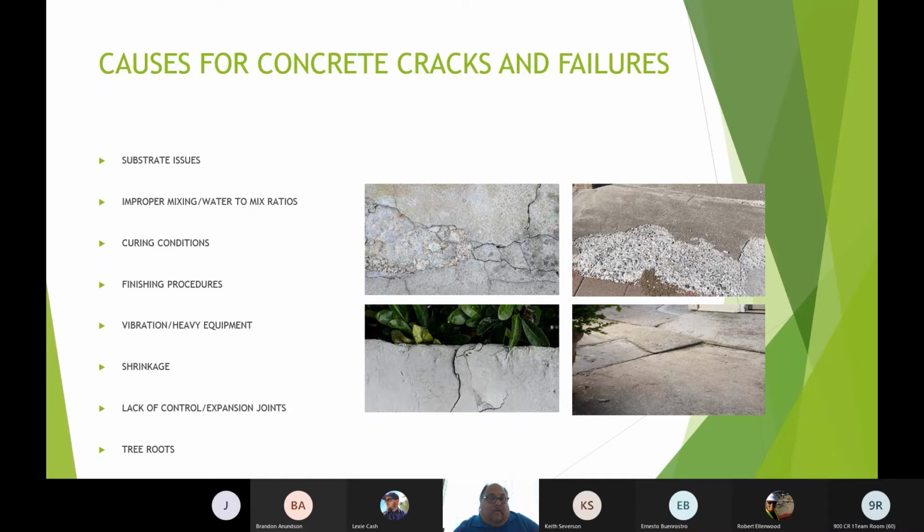I've seen so many things. They're called plastic shrinkage cracks, where they overwatered the material and it evaporated too fast. There are a lot of different things we'll get into, but you're right, Keith, a lot of it comes back to how much water you added. Did you add too much, or you think, oh no, it needs a little more, so you went halfway through and started adding more water on the end to get the finish right. You just created a 50-year mistake, because the concrete will be hard and it'll last 50 years, but you've got to look at that ugly finish the rest of your life. So yeah, very important. Good stuff.